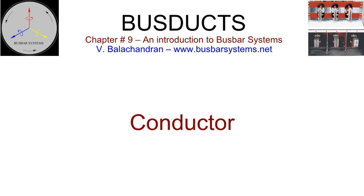Some specifications permit the conductor to be insulated, coated with an insulating material or sleeved, to decrease the air clearances, as long as all the electrical stress tests are successfully complied with, and consequently make the bus duct compact. Insulated conductors are more relevant to medium voltage than low voltage bus duct. The percentage reduction in the cross-section of the bus duct with the insulated conductors increases with the increase in the system voltage.